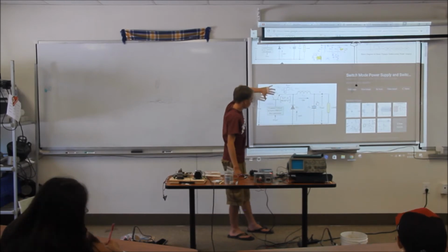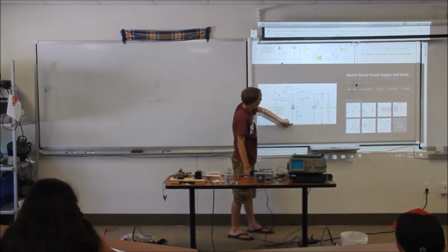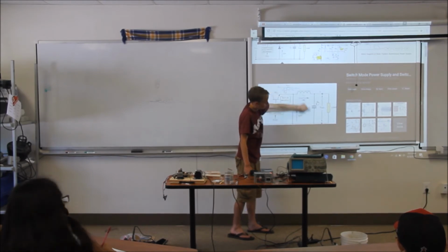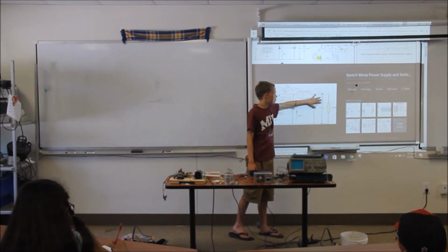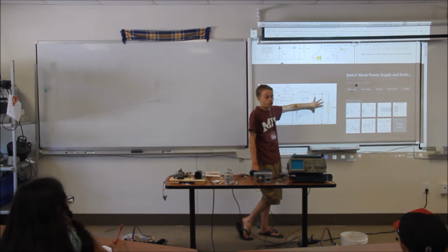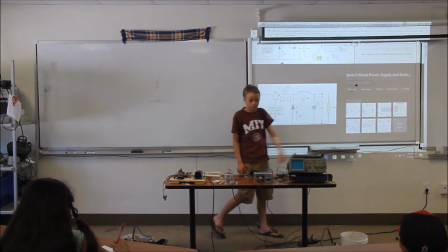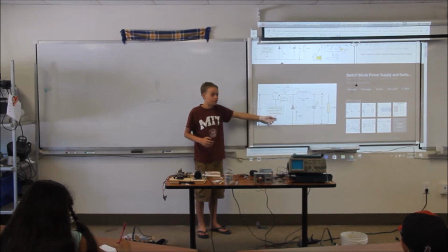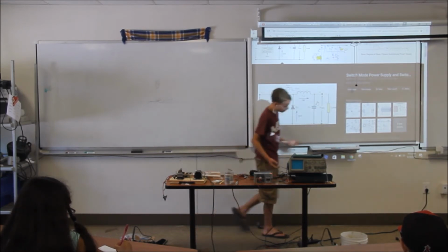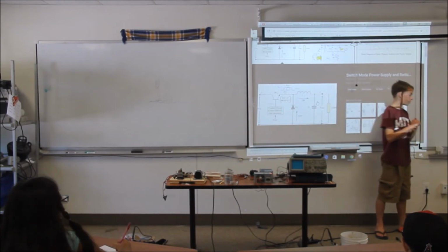Now what happens is when you turn off this transistor, that magnetic field is able to go through this diode and through this capacitor to charge it to a higher voltage, so it has super high voltage across this capacitor. That's able to run this. So if I were to put 6 volts in here and have a circuit that turns this on and off, then we would be able to get any voltage out of this side from 0 to 500 volts.